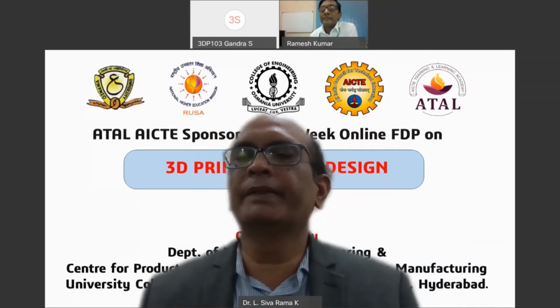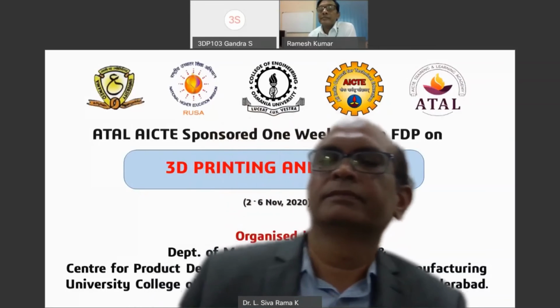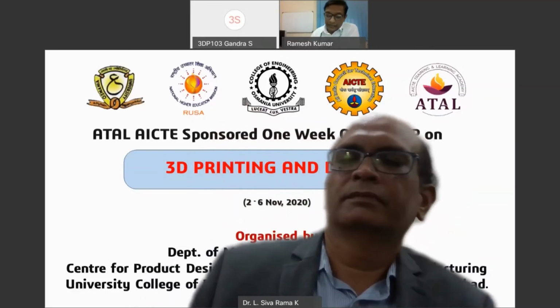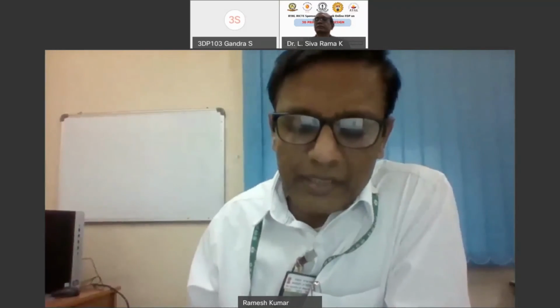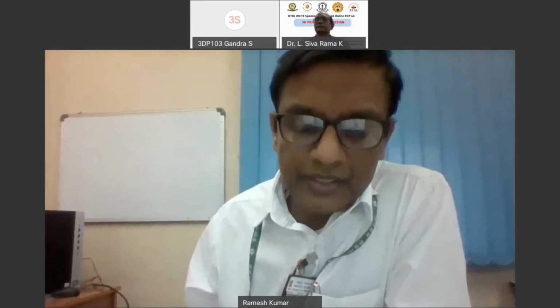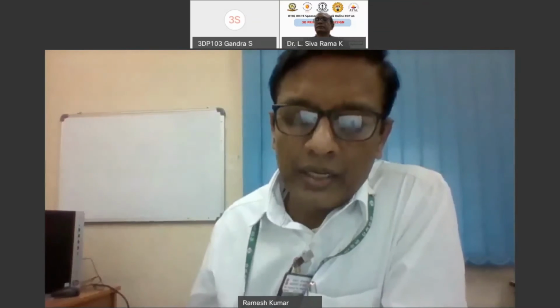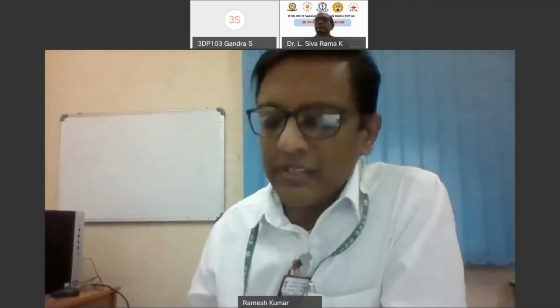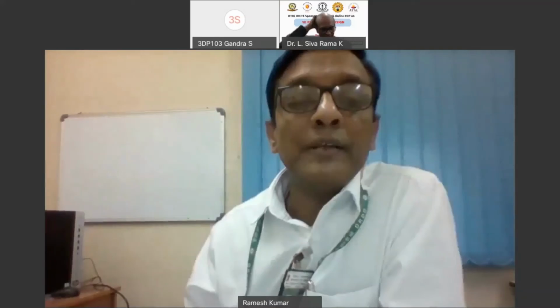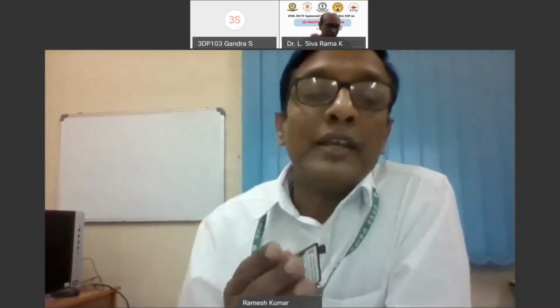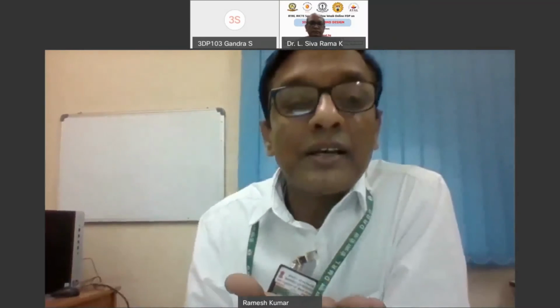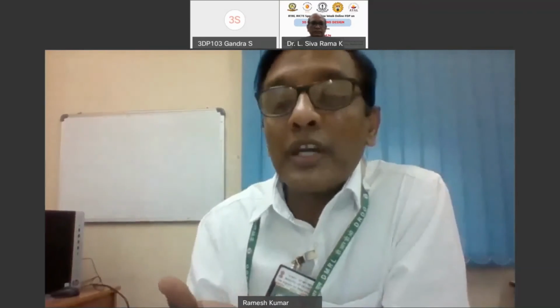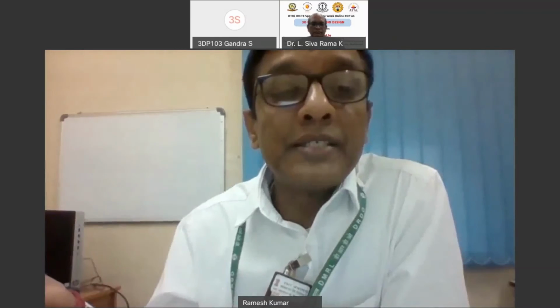Another question, sir, from Rupa Tulsi. She says, how can we control porosity? See, actually, there are three or four major parameters in 3D printing: powder feed rate, scan velocity, hatching, and power settings. We have to understand at which optimized parameters we are able to get the maximum density products.